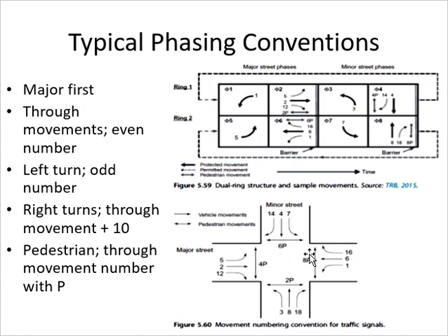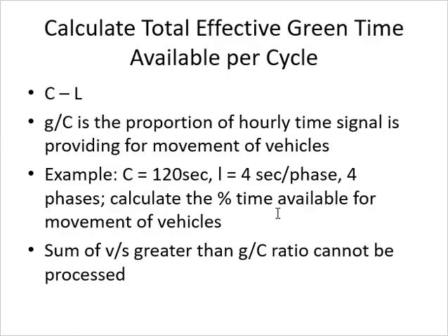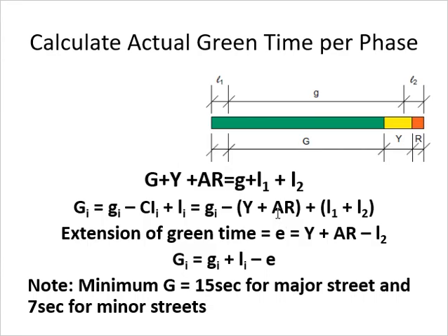So the time required by 8p will be checked against the phase time of 8. The time required by 4p will be checked against the time of 4. I'm assuming that these pedestrians should go when this parallel movement is happening, and this is what usually happens. You see the cars going in the parallel direction, you start moving.